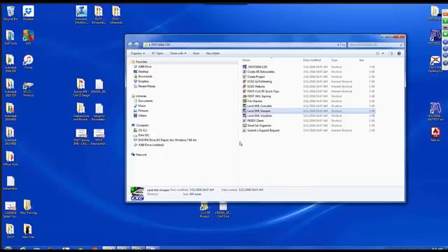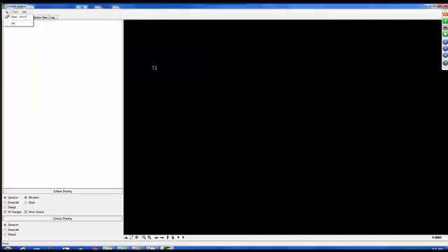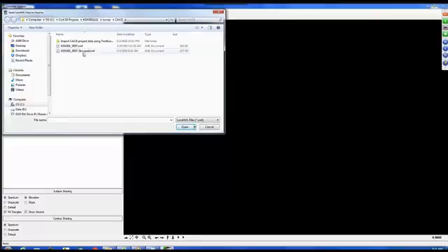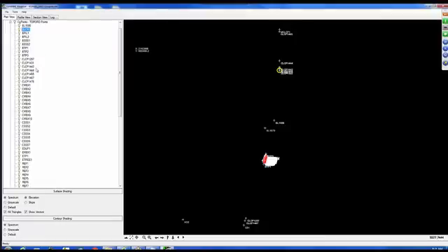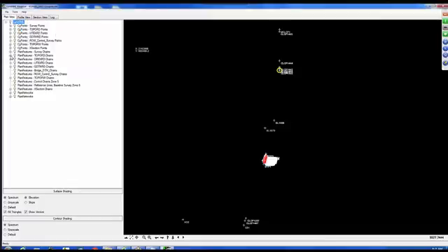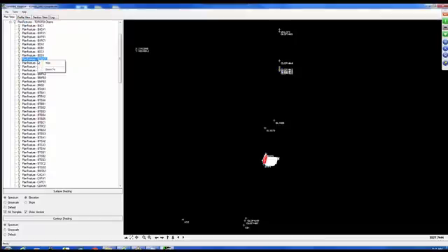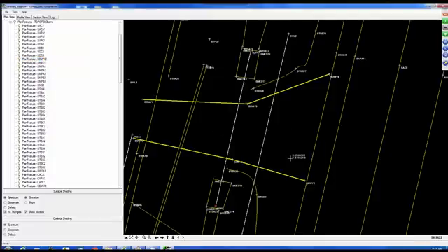Okay. Now, before I go into Civil 3D, I'm going to open up the LandXML visualizer again. This time, I'm going to open up the file that I just created that ends in grouped. Now, the data essentially looks the same, except if you look under the LandXML file, now you can see that we've got these groups built for us. So now if I pick on the TopoRD points, it's going to be listing all the points that match that search filter criteria that we did in the grouper tool. All right. If I look at my plan features for my chains, those are all the chains that are made up of that filter that just came out of the LandXML grouper. All right, so let me pick on this one here and say Zoom To, and there's the change for that particular filter that we applied.